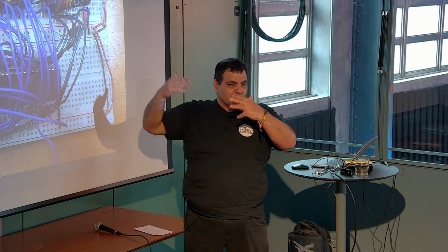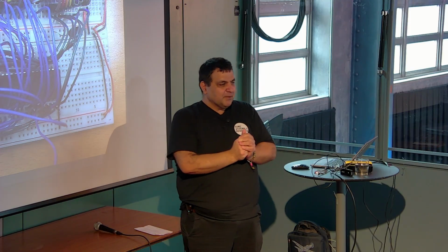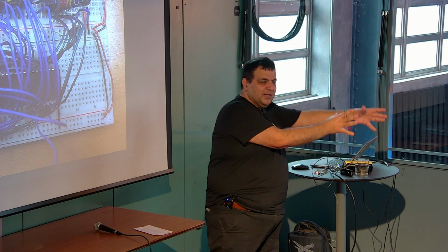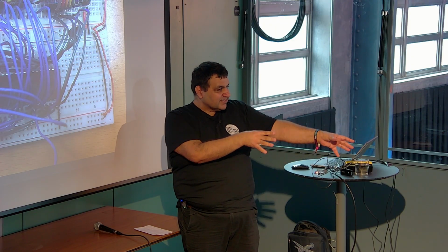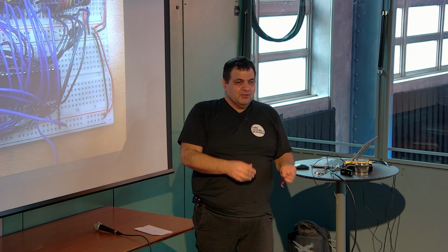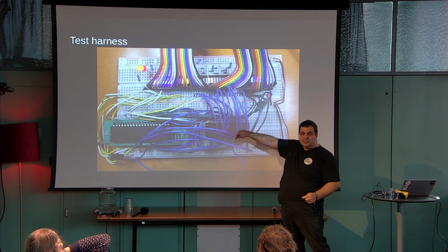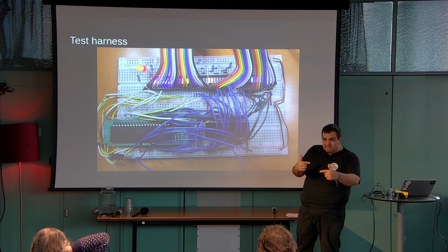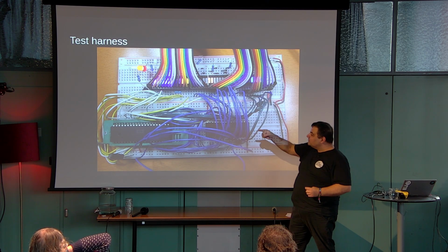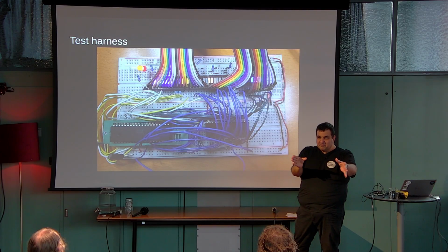If you want it to execute a program, you need to load the program into memory somehow. So you compile it with a 6502 assembler. You use Python to talk to the Arduino, to talk to the memory, to load it into memory. And then you start running the program and record what the 6502 is doing each cycle into a file.